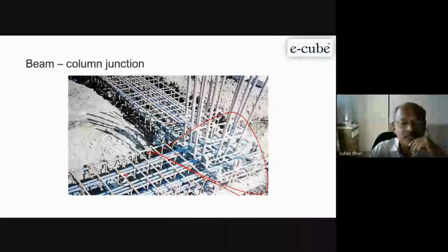Because for the concrete here, 20 mm is okay because the gap is very high. But here, if you see, the gap is not there, not even 20-25 mm. So better you go with 10 mm size. Such locations you have to identify, and an appropriate concrete mix design has to be given, and cast those particular junctions. Then only will we have excellent quality concrete and structural members. I think we'll stop here today.